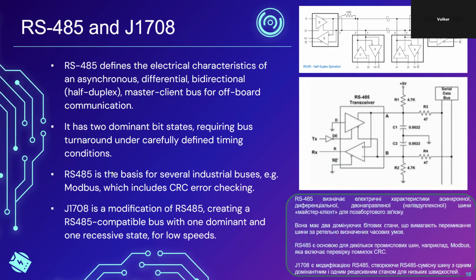And in this case, it has 2 dominant bit states, meaning if you're implementing pure RS-485, you would need to follow a very strict timing regime. If the microcontroller is the bus master for RS-485, which in most cases it would be, then after issuing a command to, for example, a sensor, it would have to vacate the bus within a very specified period, very quickly.